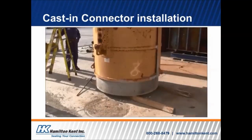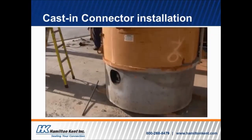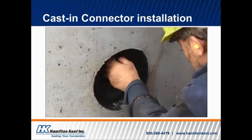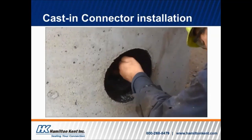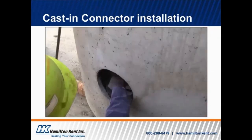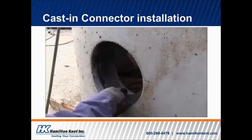Then the concrete's poured, and then the next day they're stripping away the formwork, and you can see that all you can really see at this point is the mandrel, because the rest of it is inside that mandrel. So they loosen up the outer jacket of that mandrel, and then that piece comes out. And then there's still the inner piece. So once the inner piece of that mandrel is pulled out, then you can see the connector is in that hole, and that's all you can see.